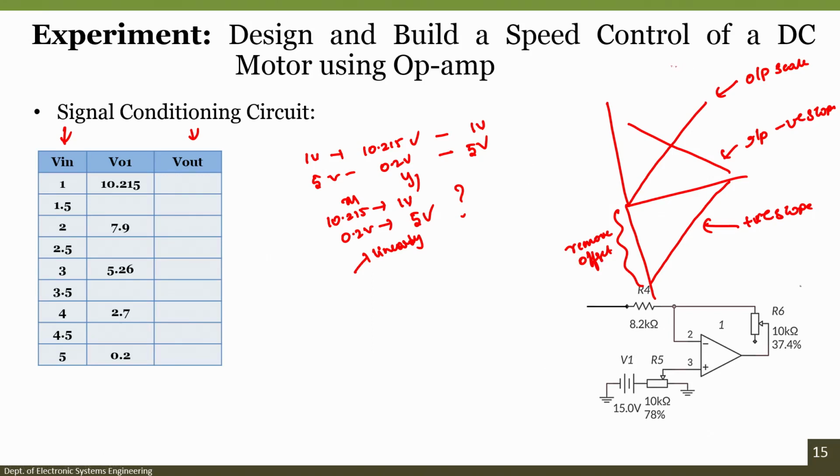Graphically it is easy to understand that I have to do the inversion and then provide an offset, so that this signal will shift from 0. But what magnitude of offset and what magnitude of slope do I have to give such that the input we provide to the system will get this output? So, we require a theoretical understanding of the conversion of this signal.